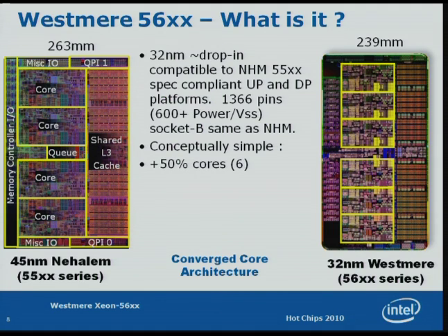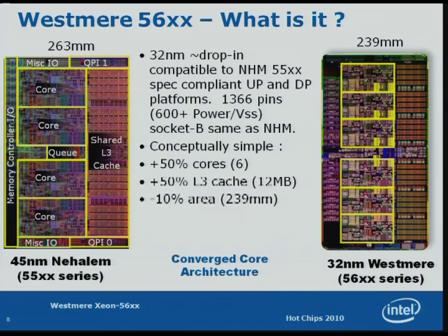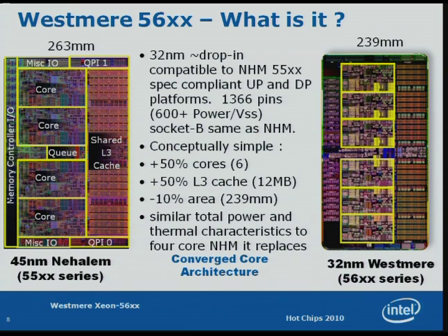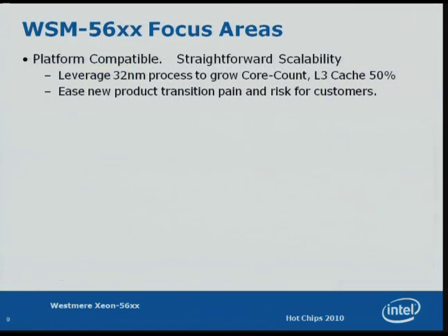So conceptually very simple, 50% more cores, 50% more cache, and it shrunk about 10% in area overall, and similar total power and thermal characteristics to the Nehalem it replaced. So this is very key to the concept of what we were trying to accomplish here. It had to fit in the same thermal envelopes, with the power supplies, the voltage regulators, all that stuff, so we could just drop it in and go.